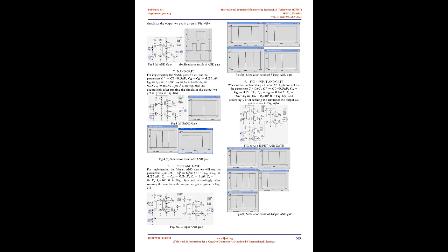Coulomb blockade interacts on the steady flow of current because whenever the high voltage, logic 1, is applied to the input, it causes a shift in the induced charge on each of the islands of the two SETs by a fraction of an electron charge and keeps SET1 in Coulomb blockade, and the other one, SET2, in conducting mode. As a consequence, the output shifts from high to low. The simulation result of an inverter is presented in Fig 1d.